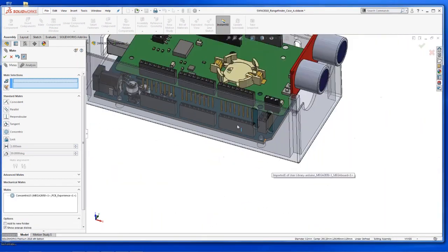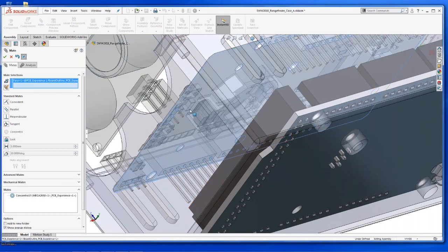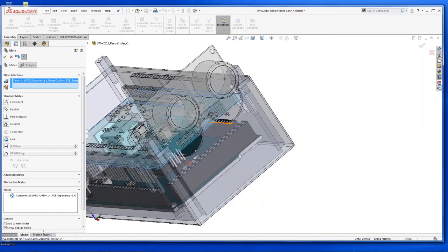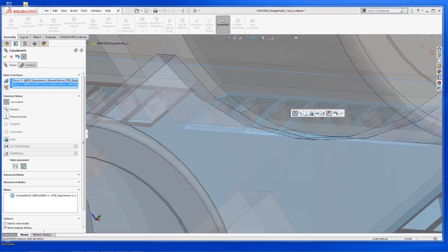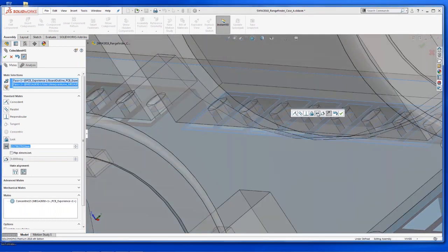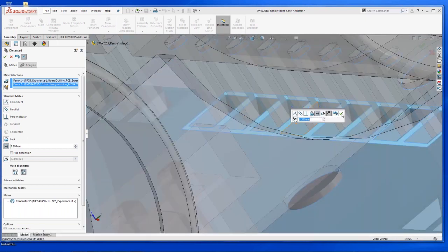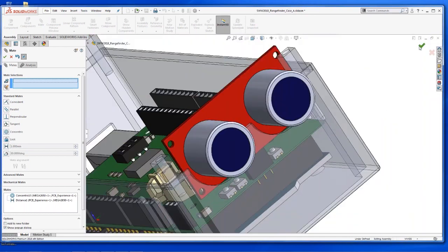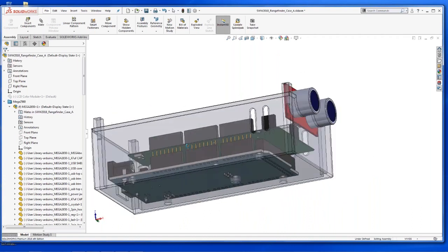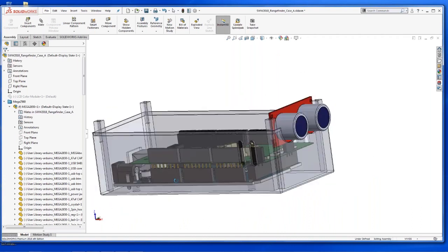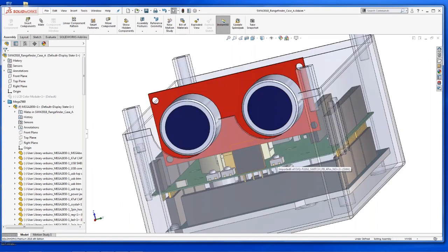Now we have board-to-board connectors, right? So we take the back surface of our board and we say that we need that inserted into the surface of this connector. But the manufacturer gives us the exact distance, 3.2 millimeters. So with the 3.2 millimeter offset, you can see now that we have that assembly similar to the presentation slide. However, we've got collision of the rangefinder into the chassis.